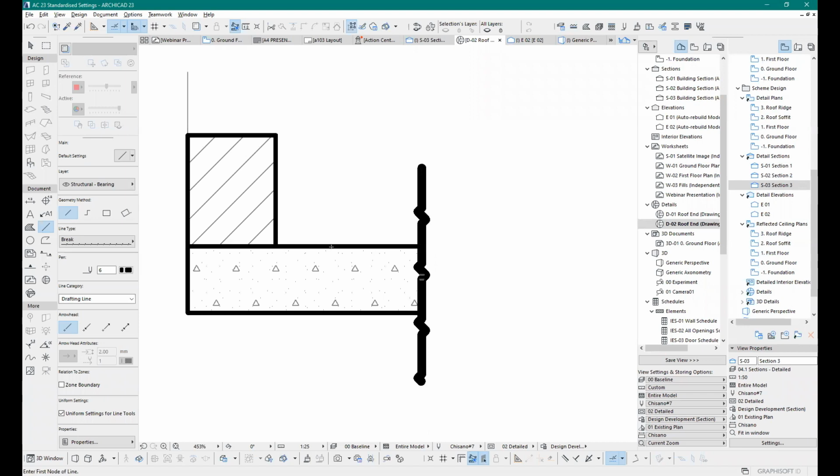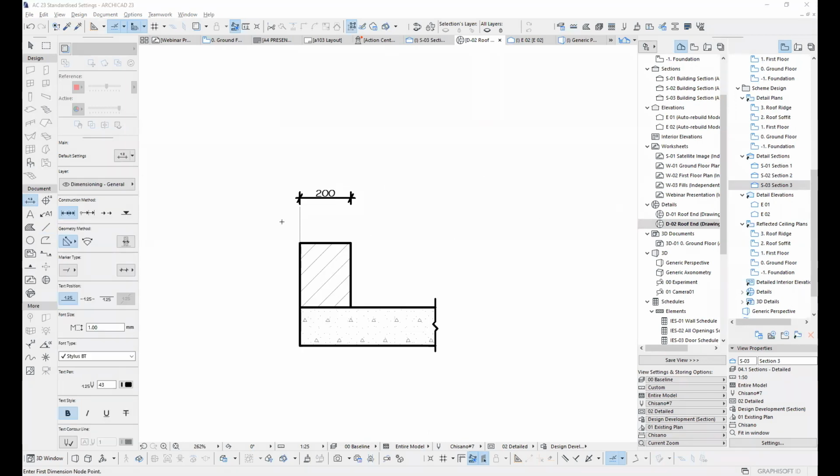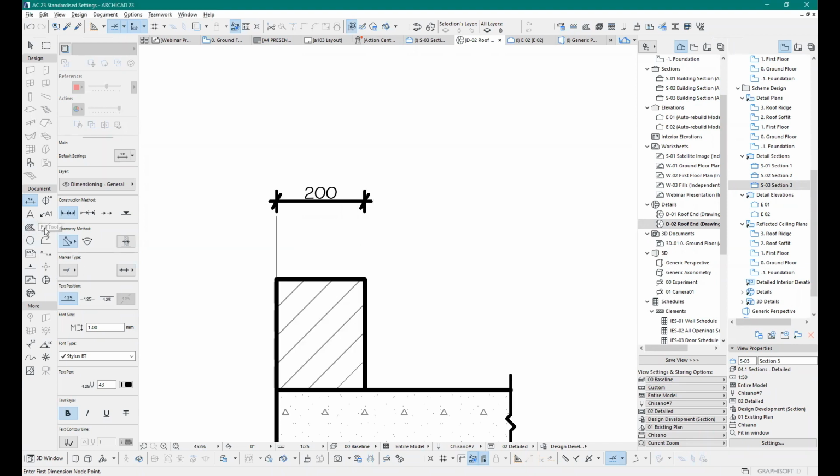So the process of annotating is just as you would do in any other drawing. You either use dimensions, okay, sorry for that. I just created another line giving me dimensions. So let's click on the dimension tool, click there. So as I was saying, the process of annotating a drawing is just as you do in any other drawings, by using your dimensions, your labels, your text tool.